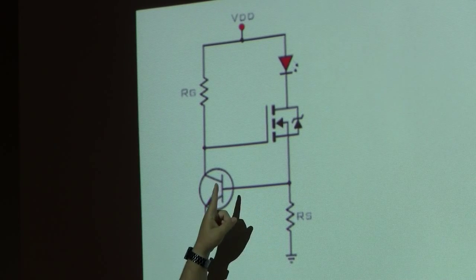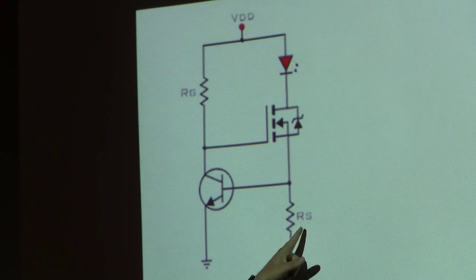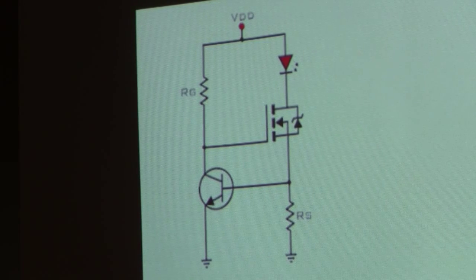So you're going to drive through that diode, or whatever your load would be, 0.6 volts divided by that resistor. So if you have a 0.6 ohm resistor, you're going to drive 1 amp. It doesn't matter what your load is. You could have a 1/10 of an ohm resistor, which should be drawing 120 amps from the 12 volt supply, but use a 0.6 ohm resistor there and it'll drive at 1 amp.